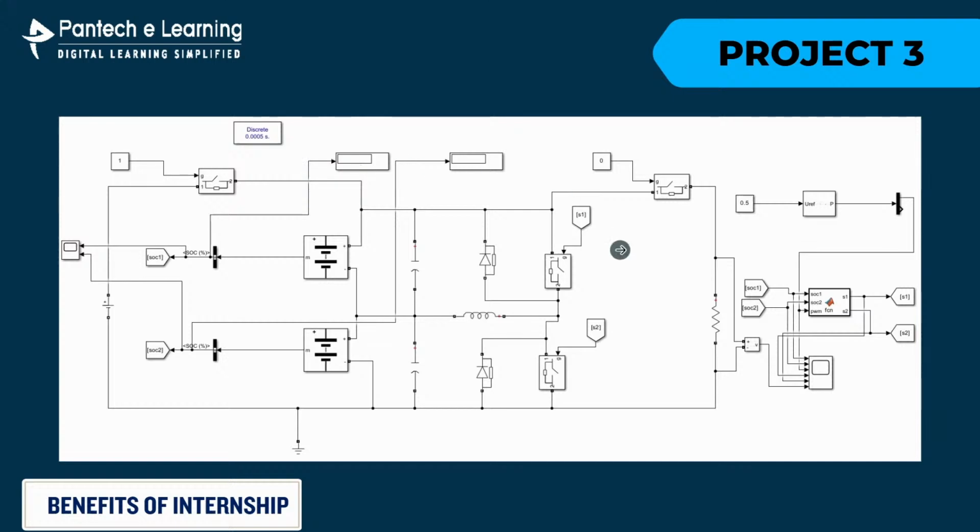So project 3 is cell balancing. We have to know about cell balancing and do it, because inside the battery pack we have a lot of cells connected in series or parallel form. We have to balance all the cells inside the battery pack to improve the efficiency of our electric vehicle. There are 2 types of cell balancing methods available: one is passive cell balancing, another one is active cell balancing. This project's simulation is an active cell balancing. So this is project 3.